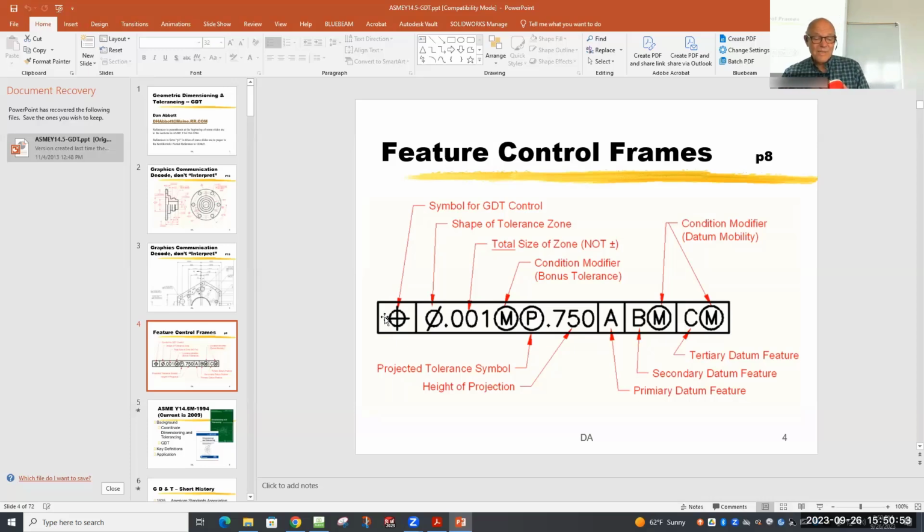And not only does it control the location, but it also controls how straight the hole goes through something. So if you're looking at a hole, suppose I have a part, and that part is this thick right there. There is an axis to that hole. You can't see it. It's artificial. It's imaginary. But I'm going to pretend that the axis is this. So the axis of the hole is what determines not only the position of the hole, but also how straight the hole is. So if you have an axis, a center hole like that, if I move the axis, it moves the hole around as well.